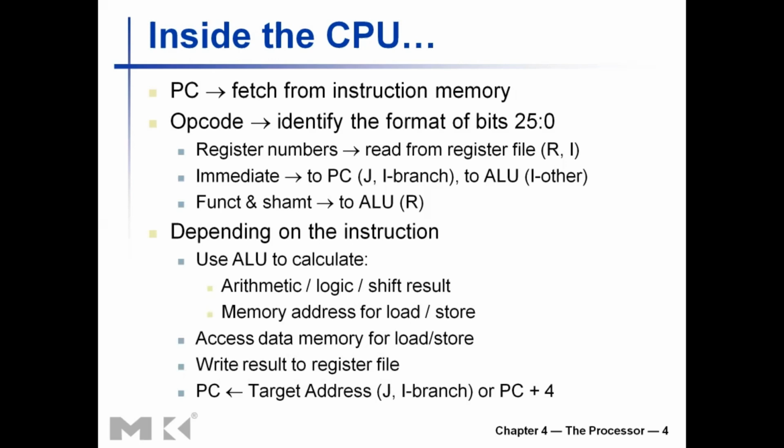The next things to be done are different for different instructions. For example, for arithmetic and logic type instructions or shift instructions, you need the ALU to calculate the corresponding arithmetic operation, addition or subtract, or the logic operation, AND or exclusive OR, or the shift operation. If it is a load or store type instruction, you need the ALU to calculate the memory address, because